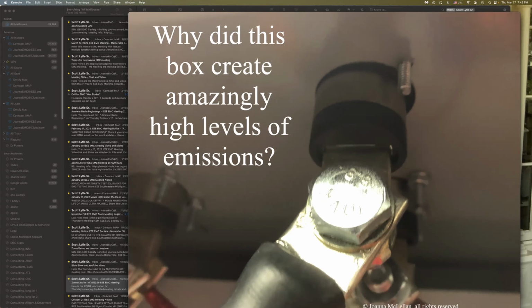Yeah, we had that problem in a solar deposition machine because we were trying to couple our power into a plasma. We had transmission lines and splitters inside these vacuum chambers trying to couple power into the plasma. But the mechanical engineers had no idea what impedance was, and had made no attempt to match the impedance of the transmission line to the plasma. And so there were huge standing waves, high voltage, high current all along the line. It would arc over and everything. It was just about a 1-hour consultation where we worked out the impedances of the various portions of the line, made a few geometry changes, and all of a sudden the power coupled way more efficiently. There was no more arcing, no more high voltage sections, and everything was fine. But that was just because the people who designed this had no idea that radio frequency power had impedances, that it mattered, and that you had to try to match something.